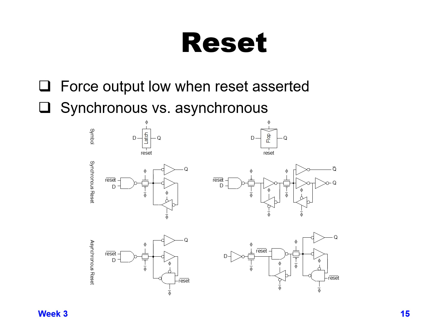A synchronous reset says, wait for the clock to actually capture a new value in the latch, and the new value that it captures in the latch or the flop will be the reset value. So a synchronous reset can be done by taking reset bar, NANDing it with your data value, and sending that into the rest of the element, as if it was the value you're capturing.